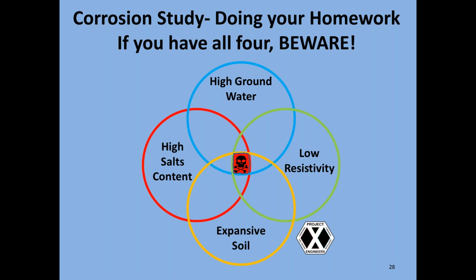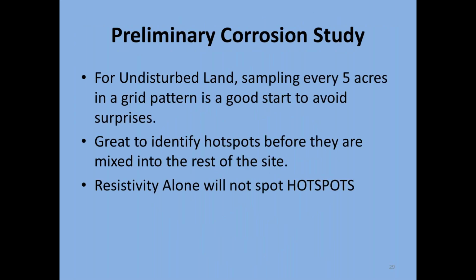One easy rule of thumb is farms: wherever anything grows easily, if there's a ton of vegetation somewhere, it's a very good sign that it's a very corrosive site, because obviously there's a lot of nutrients in the ground. Plants grow best in low soil resistivities, because they have to have that ion exchange too. So if you see a lot of vegetation and you think, wow, this is a tropical jungle here, that's a good sign the site is very, very corrosive. Now, this is interesting.